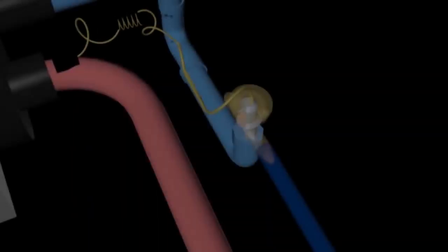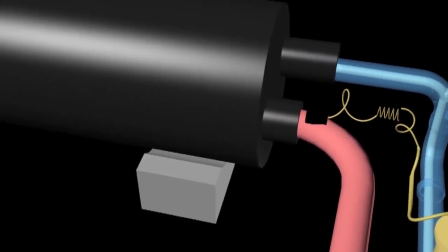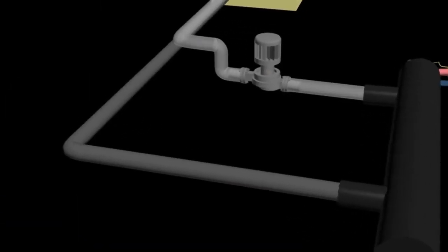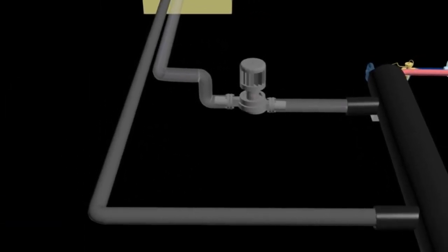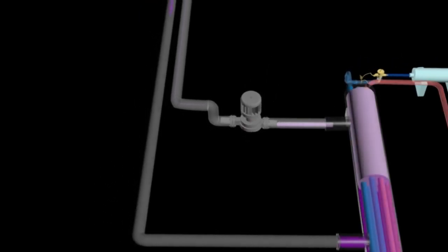Evaporator. The refrigerant in low-pressure liquid form coming out from the expansion valve will flow into the evaporator at low temperature. In the evaporator, the heat from the chilled water which comes out from the air handling unit will be absorbed by the refrigerant due to the temperature difference produced.